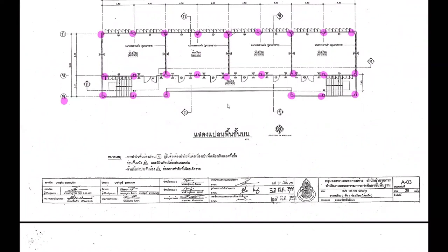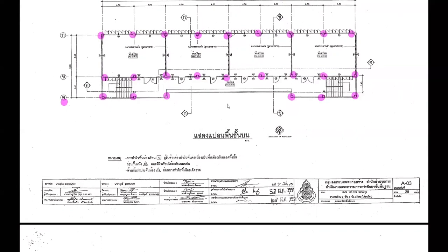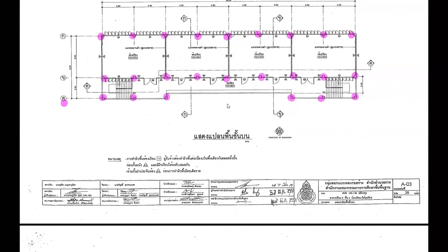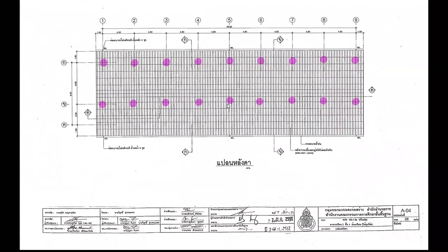at the corridor. But if you can recall your school, let's say this is what the architects call a single corridor. It means that you have a corridor and you have rooms on one side only. If you have rooms on both sides, it's like an apartment maybe, that becomes a double corridor. Now in a single corridor, nobody wants to have columns around here. This is a corridor, they want a clear view. It's going to be quite ugly to have columns around here at the corridor. So chances are you're not going to have the columns around here.